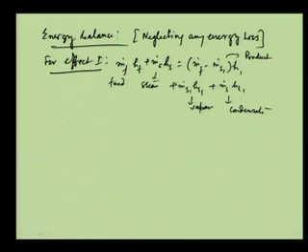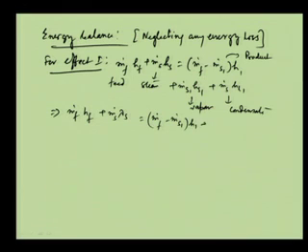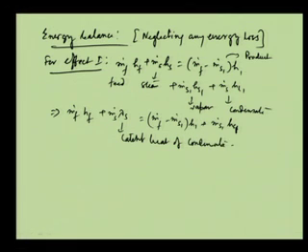So, from there we can write, in terms of latent heat, m dot f h f plus m dot s lambda s, the latent heat for this first effect, and that will be equal to m dot f minus m dot s 1 into h 1 plus m dot s 1 into h s 1, this is for vapor. So, this is becoming that, and this is the latent heat of condensation.